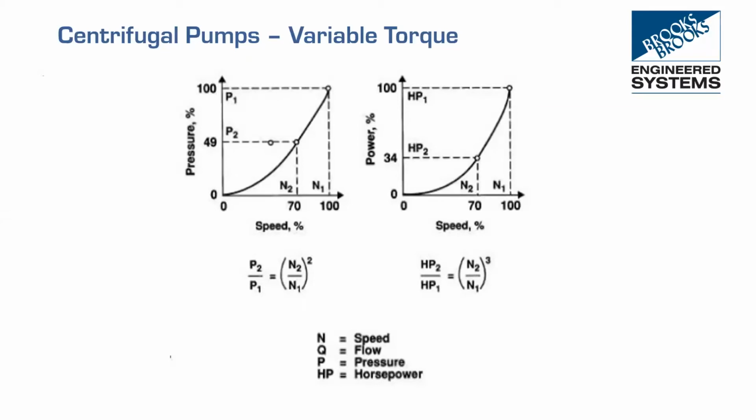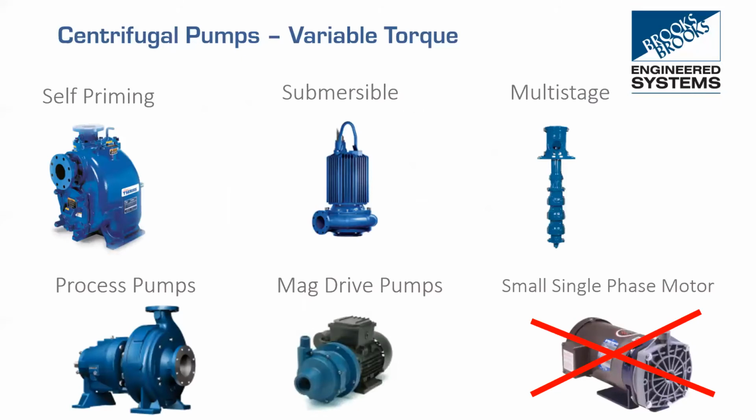Because of that, VFDs that are used for variable torque applications can be a little bit lighter duty than VFDs that are used on constant torque applications. The stress is usually at the starting range of the VFD when it's close to 0 hertz, and there's very little required for variable torque loads at near 0 hertz. Okay. And here's some examples, Adrian.